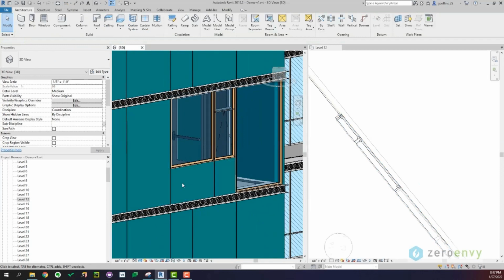So we will use doors. So there are different approaches on how to deal with spandrel panels. Our go-to approach is just use doors because I think it's pretty hard to split a wall into multiple pieces and assign thermal constructions to them. The more straightforward way would be just using a door to represent spandrel panels, and you can create a unique construction for the door. So we will do that in Revit as well.